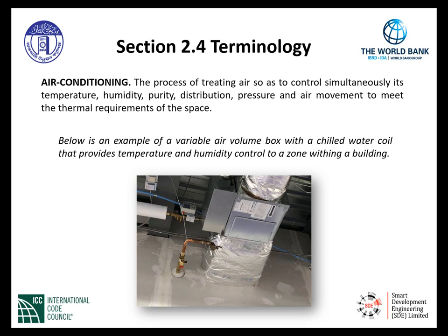The term air conditioning has a very specific meaning. Air conditioning is the process of treating air so as to control simultaneously its temperature, humidity, purity, distribution, pressure, and air movement to meet the thermal requirements of the space.